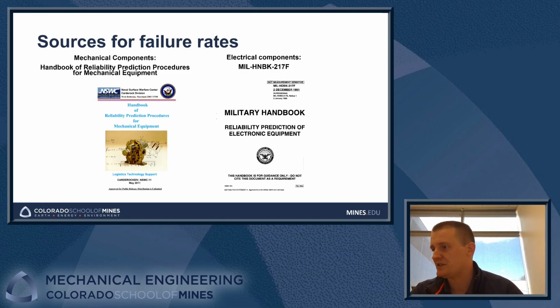So any of your transistors, relays, resistors, circuit boards, anything like that you want to know how reliable it's going to be, that's where you're going to find it, is in Handbook 217F. All right. I've linked both of these resources in the PowerPoint slides, which you should be able to download from Canvas. You can go and grab the links from there. You can also just Google these resources. They're out on the internet, freely available, and just download a PDF so that you can have them for your reference when you're doing your calculation.